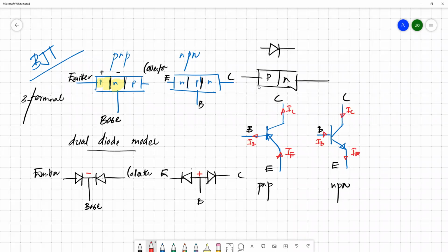Okay. So for this transistor operation, we basically discuss two types of analysis. One is called DC analysis. The second one is called AC analysis. So why do we have these two types of analysis? You may be aware that transistors are basically used to implement amplifiers. An amplifier is a kind of arrangement where you can boost your input signal up to a certain level, or have a gain between output and input. For example, an audio amplifier: whatever the input of a mic is amplified and fed to a speaker.